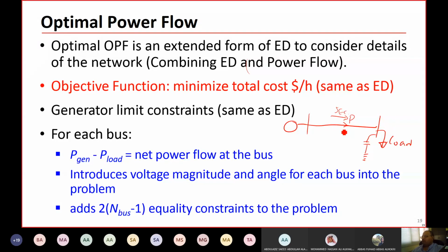This will reduce their bill, reduce the loading of this transmission line, and improve the power factor here, maybe to unity or to 0.95 lagging, depending on how much reactive power comes from the capacitor and how much reactive power the load needs.